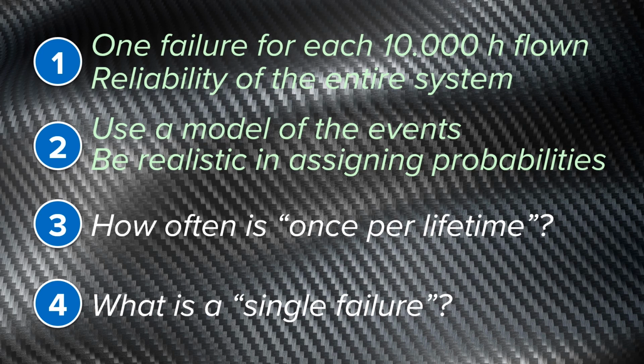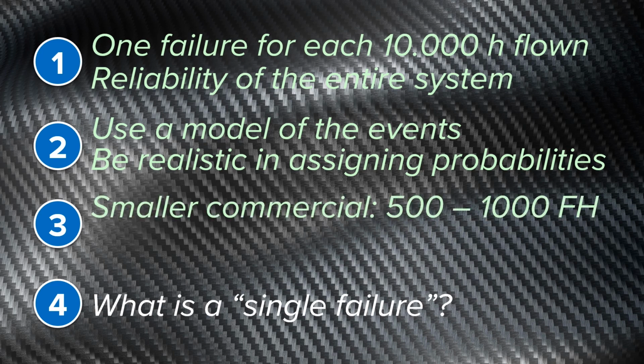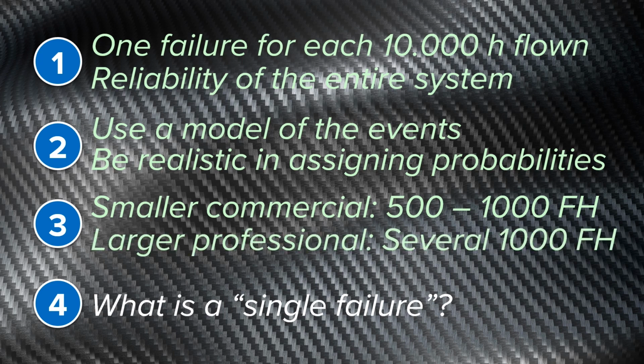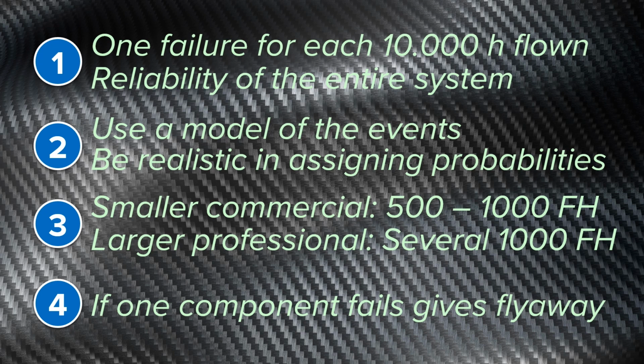Question 3. How often is once per lifetime? For the smaller commercially available drones, the lifetime would typically be 500 to 1,000 flight hours. For the larger professional systems, it will be several thousand flight hours. Question 4. What is a single failure? If there is one component in the drone which can lead to a flyaway if it fails, then we say that the drone has a single point of failure.